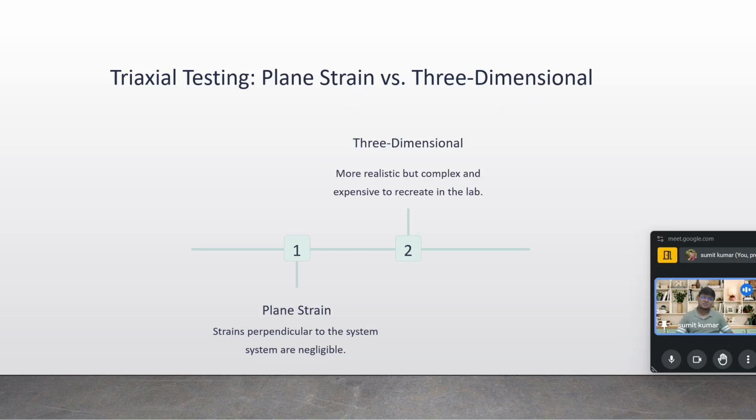If you are professional engineers, you can see in the soil report that the triaxial test is never performed very often, because it is time consuming and sophisticated, and expertise people need to be there to perform those tests. Basically, when I discussed the triaxial test, we came across A and B, that is the Skempton parameters.